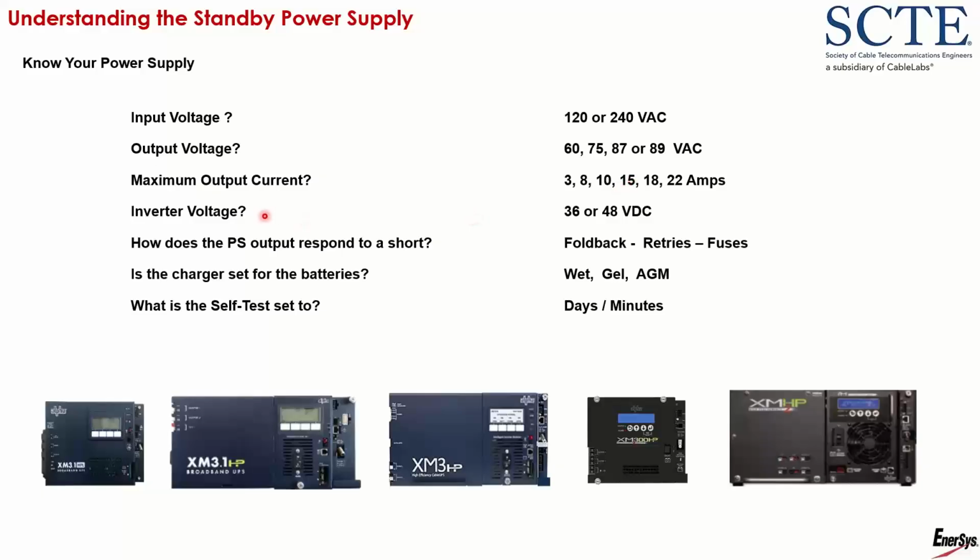My inverter, is it a 36 volt or 48? Or I should have had on here, is it a 12 volt? Some inverters are only 12 volts. What happens to my power supply when there's a short on the cable plant? Does it go into foldback? Does it start to cycle? Do I have fuses? Do the fuses blow?